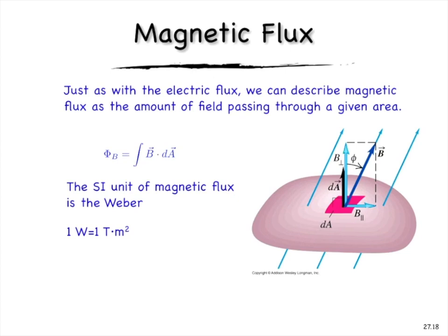And the same is true for the current flowing through the top and bottom. You can check that if you want. At the top, current is flowing out of the page, so the field is going to the right. So all these wires are producing fields that inside the coil add up to the right, and hence I get a flow of field lines going through the coil from left to right. And then when they leave the coil on the right, they must loop around. And so this looks a lot like that. In fact, it looks identical to that. So now you know why this coil of wire acts like a magnet.